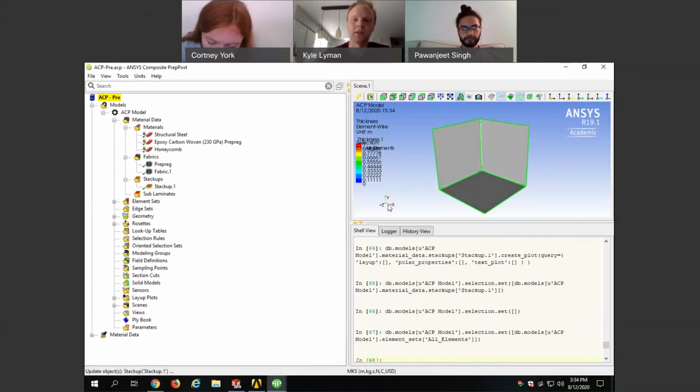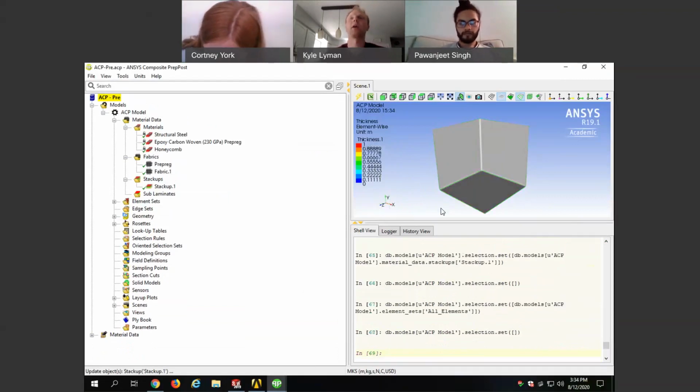So right here, this is a global coordinate system, meaning the whole model references this coordinate system right here. You can see. But when you're talking about carbon, we want to orient the carbon fibers differently if we need strength in certain areas or less in certain areas. The orientation becomes really important.